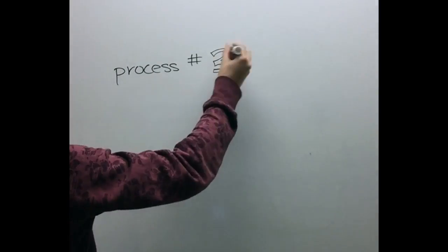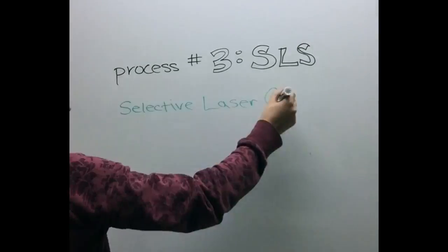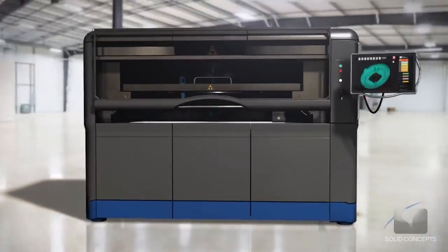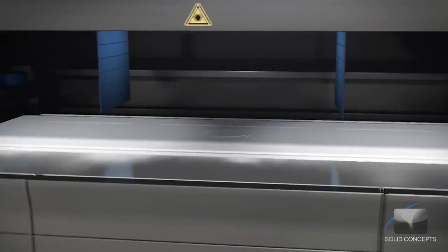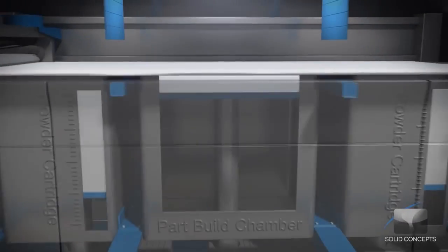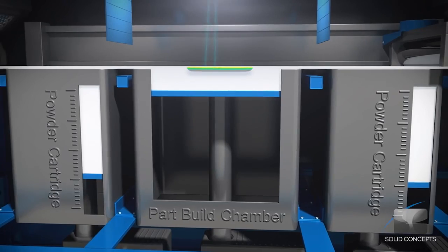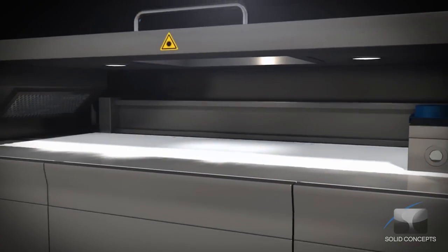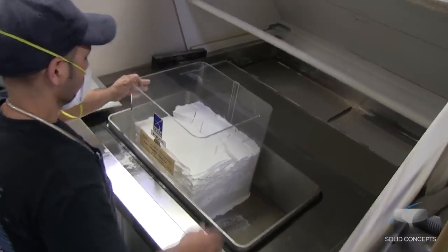The final of these 3 processes is called selective laser sintering, also known as SLS for short. In this process, a powder polymer coat is brushed and rolled by the machine, as a laser activates, again, an image in the XY plane. As the layer finishes, a fresh coat is already being applied to be re-rolled and activated by the laser within specific dimensions of the part. The excess powder acts as a form of support for the finalized product, removing support attachments from the equation of this process. After removing the excess powder, the part is removed and brushed.